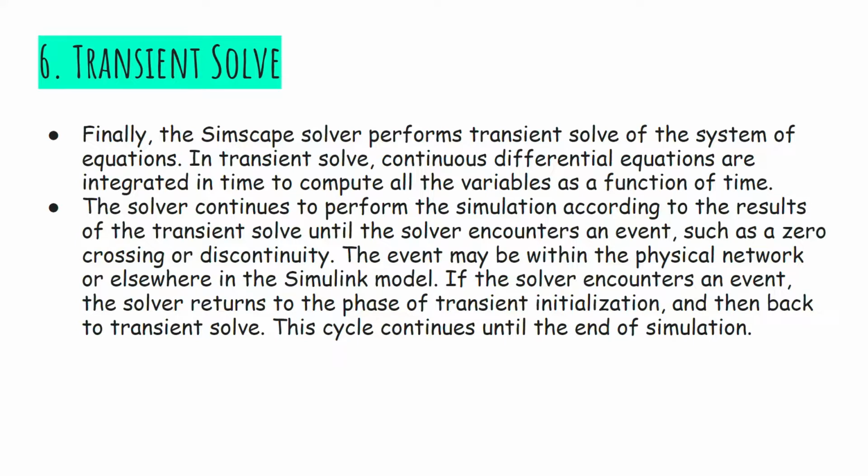If the solver encounters an event, the solver returns to the phase of transient initialization and then back to the transient solve. So this cycle will continue until the end of simulation. So that's how the Simscape simulation works.